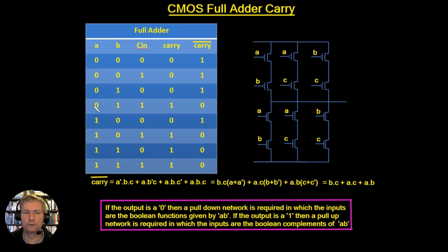In order to get the 0, there would be a not A, B, C, and that is that not A, B, C here, and then we could go down to the next 0 here, and it's going to give us our A, not B, C. That's A, not B, C. We can go down to this 0 here and give us A, B, not C, A, B, not C, and this one here is going to give us the A, B, C, and that's the A, B, C here.